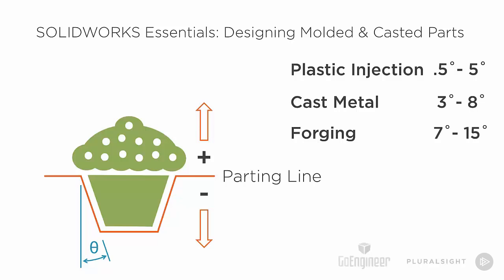Especially on that last one, what we're trying to do is take a piece of semi-pliable metal and hammer it into place. And so we need to open up that taper or that draft angle as much as possible to be able to grab and pull the material into the mold. We're trying to condense that as every drop of the hammer, we're going to try to pull that material and condense it. But if we get too flat an angle, all we'll do is cause the mold to just flatten the material out and actually squeeze it out into flashing. And so it's a delicate balance between trying to gather the material versus squeezing it out or just hammering it flat.